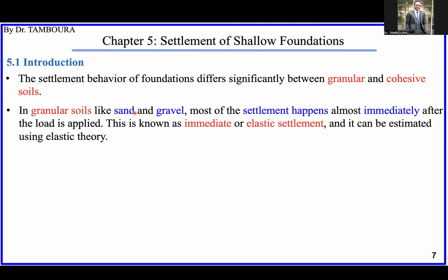For granular soil, after building your foundation on the ground, the settlement will happen immediately. It means the full settlement will happen rapidly, it doesn't take time. This is because granular soil, like sand or gravel, has a big amount of void, so if there is water, that water will escape easily and faster compared to clay.